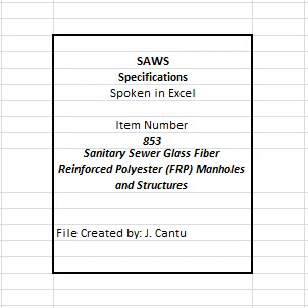C. Milestone 3, 20% of LS, sanitary sewer manhole and structure encasement and testing. This pay item includes manhole and structure concrete encasement, rebar, HDPE throat/grade rings, ring and cover, surface restoration, includes all manhole and structure testing in accordance for leakage, separate and independent of all other sanitary sewer piping. Furnishing and placing all materials necessary to complete the work is included in milestone 3 and must be completed prior